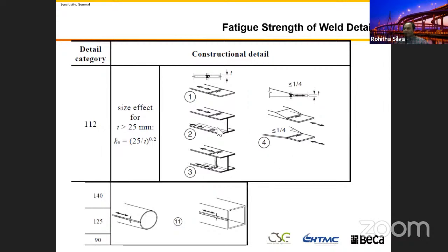For example, in here, if you get two I-beams and connect them together, if you weld around the full two I-beams, with a full penetration weld around the whole perimeter of the beam, you can see the strength of the beam. If you use a 350 MPa structural steel, your fatigue strength is only 112. It doesn't matter what your initial parent material strength is, the codes give you the strength based on the number of stress cycles. I will show you this one.